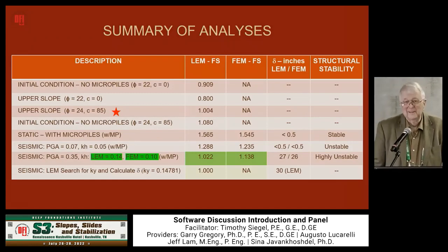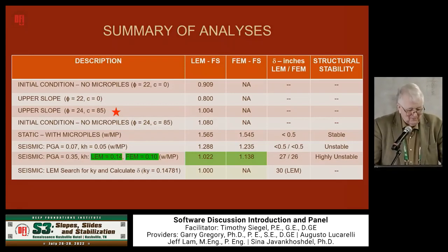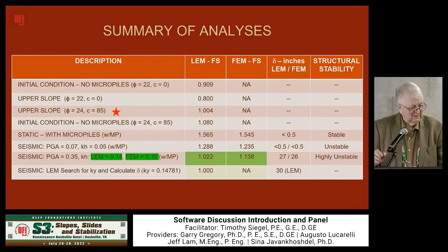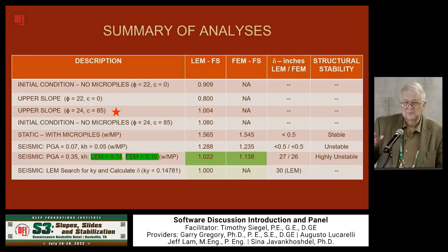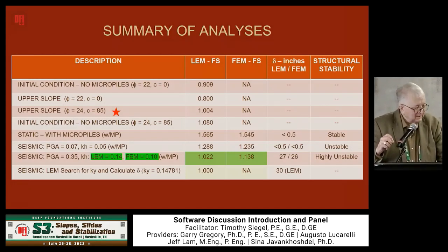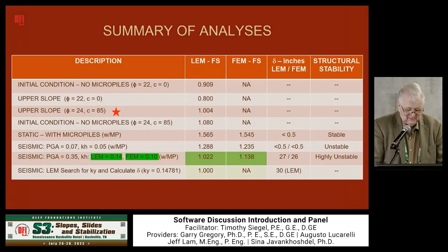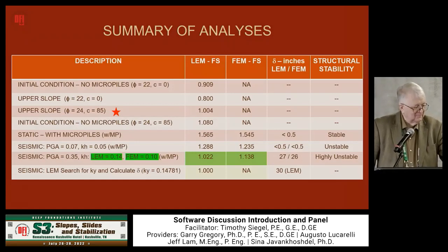And the calculation of that's not really limit equilibrium. I have an option in the program to use Newmark's simplified method, which is not the full double integration of the ground motion for the sliding block. It's simplified equations that he presented in his 1965 Rankine lecture, where he showed you could use these equations to get the maximum probable displacement. And some of those criteria have changed since then, so it's an updated version of that. And so the system, the structural system, highly unstable. And for the seismic case of Y, where factor of safety equals 1 is 0.148 approximately.